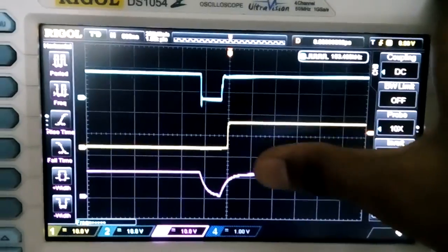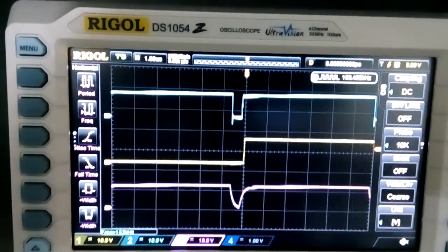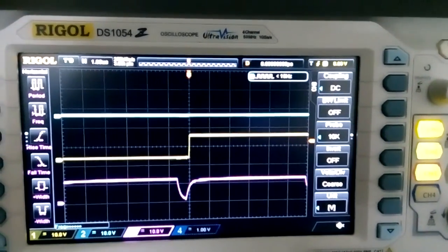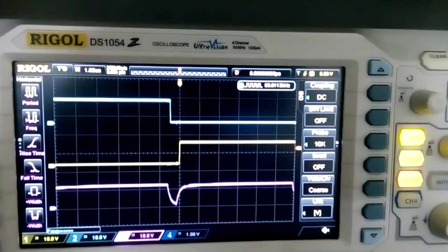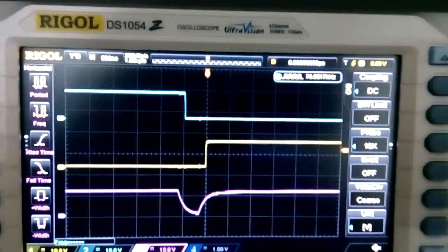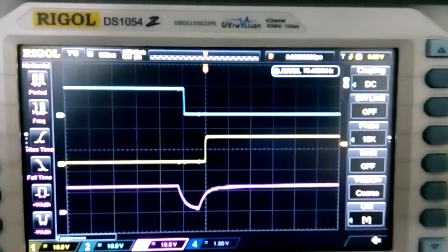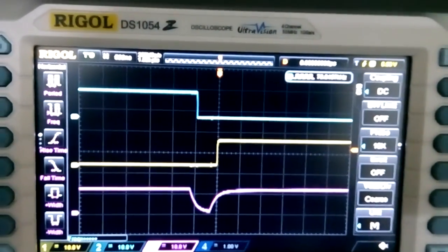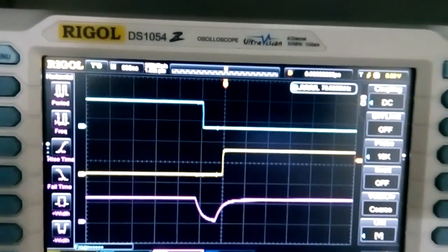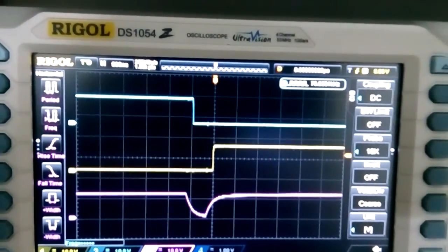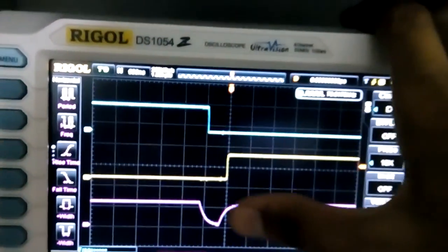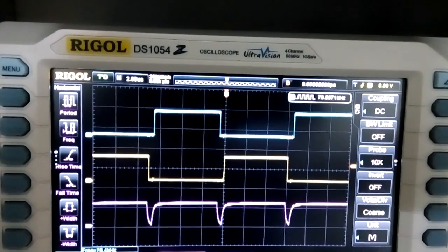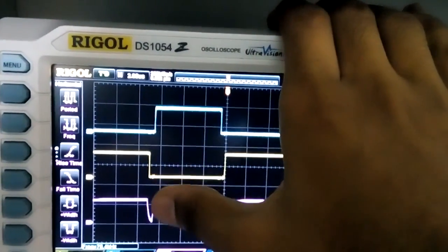So the dead time, maybe I even need to bring in another channel on this for you to understand properly. I'll do that on channel 2, which is going to probe the inverted output. So you can very clearly see this. Only when both the inputs are high, the clock pulse turns on. Not a very clear representation, but I think you get the point. Same thing with this discharge curve. So this RC thing adds somewhat of a delay between these two pulses.